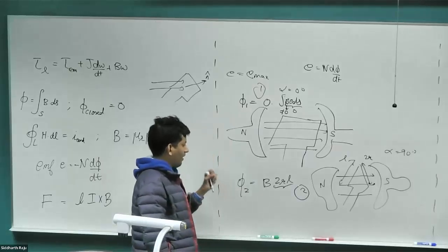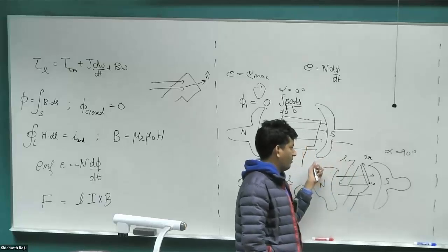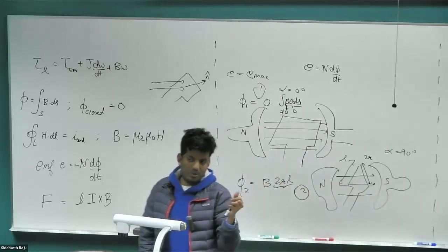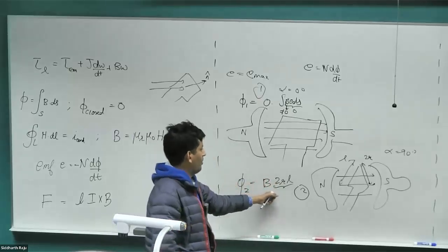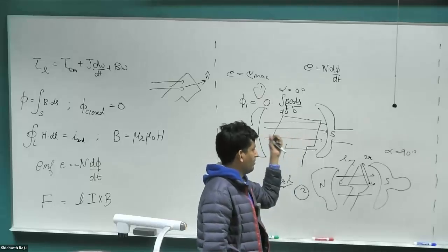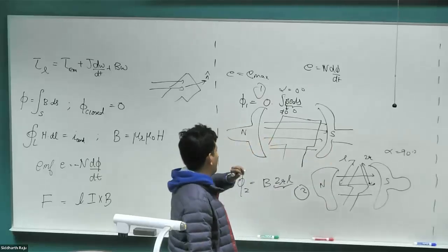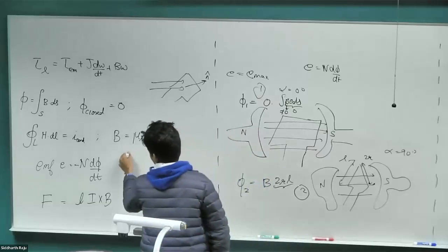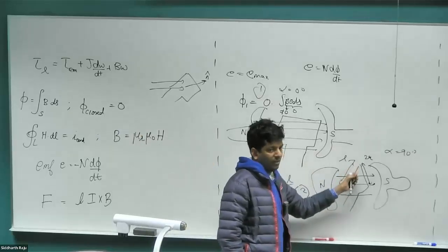Again, it's very counterintuitive because you would somewhat think, hey, if the flux is maximum, that's when the EMF would be maximum, but that's not the relationship between EMF and flux. It's the differential of flux. If the flux is maximum, it doesn't matter. It is whether the flux is changing or not. You could be traveling at 100 miles per hour, but if your velocity is not changing, there's going to be no acceleration on you. So the magnitude of the flux itself doesn't matter, the rate at which it changes is what matters. Somewhat luckily for us, through all these nice equations we have, the EMF is 0 when the windings are at 90 degrees.